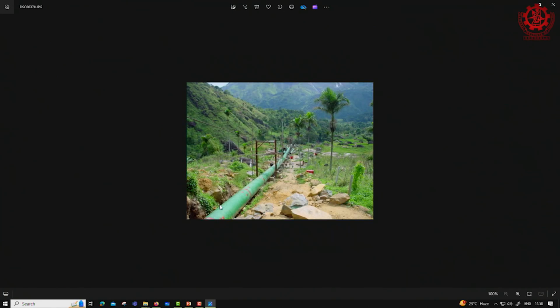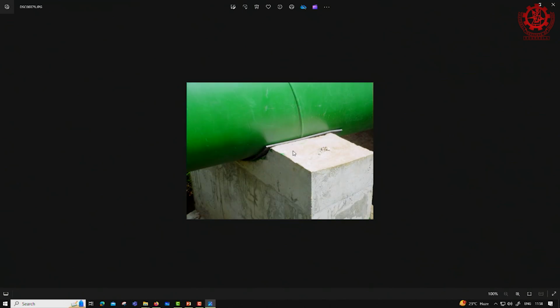Now, this is after welding, this section has been completed. You can see they have even put this anti-corrosive or other paint scheme on the welded areas. You can see the supports are here regularly. I showed you earlier how you keep the pipe on supports, either a smooth steel piece with grease, or a nitrile, strong rubber piece, to avoid damage, because in the expansion it will move up and down and thereby the paint will get damaged.